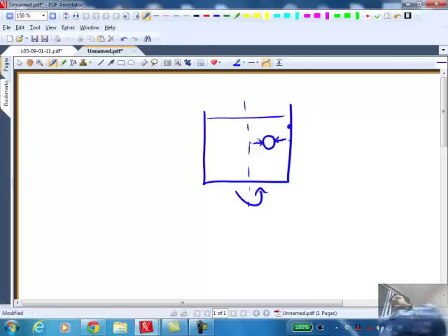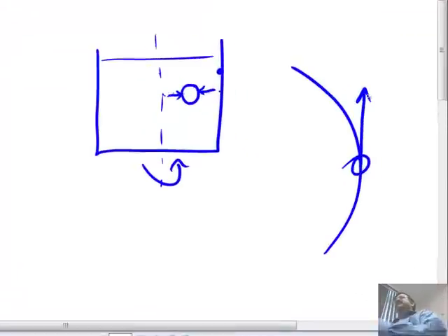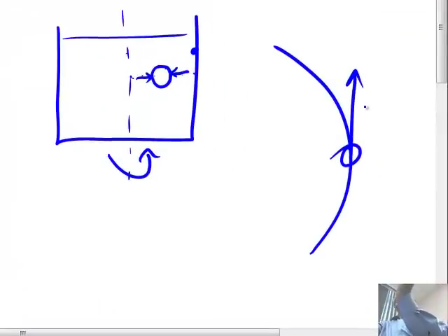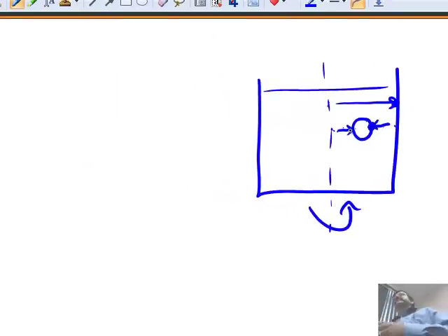So it's a force. In a sense, we can think of it like this. If you are going in a curve, the body wants to go straight. So there has to be a force that is changing the direction all the time. That is what we call the centrifugal acceleration. And that creates a pressure variation in this direction that keeps on increasing. So on the outer point, the pressure is going to be higher than the inner point. We will do a problem in one of your assignments where you figure out what this pressure difference is.